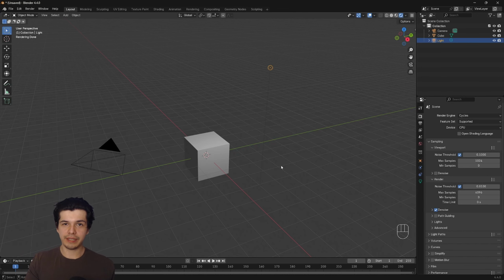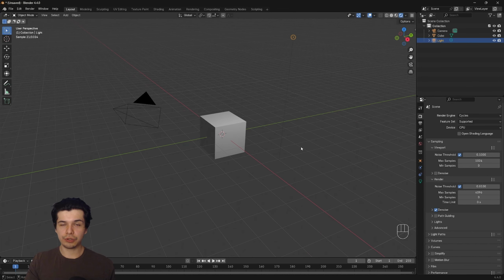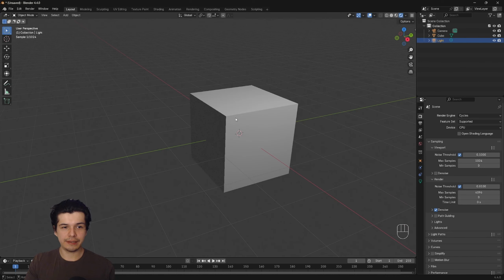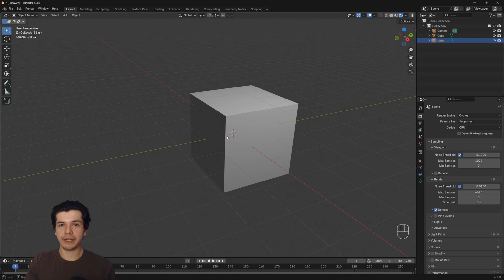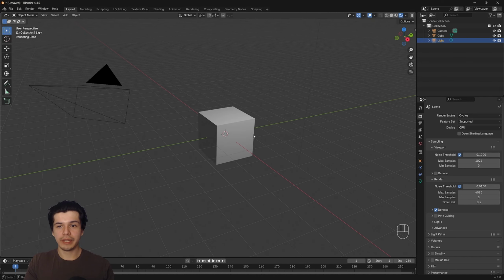You will notice that it's lagging for me. What's cool about Cycles is that it's for more realistic projects, because it calculates everything physically. If I zoom out, you can see this noise, and I'm also probably lagging, so it's very heavy on my computer, and it will be for you too. That's because right now I use CPU. Later in this series I will show you how to switch it to GPU. If I switch to GPU, it's gray, it doesn't work. You have to set it up. We don't have to worry about it, just so that you know it's here.